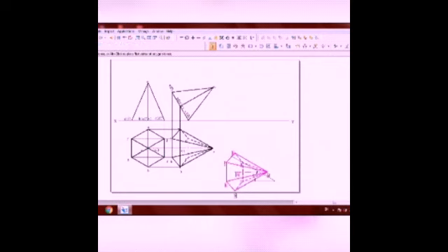And then the next command is the rotate command. You have to hold the corner again for the rotate command and select the edge on which it is resting, and then rotate it, aligning it to the 30-degree line. This time multiple copies should be switched off. So it is aligned, and if you are in doubt you can zoom in and correct it.